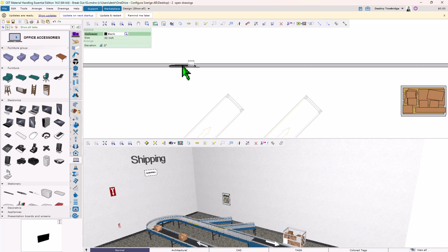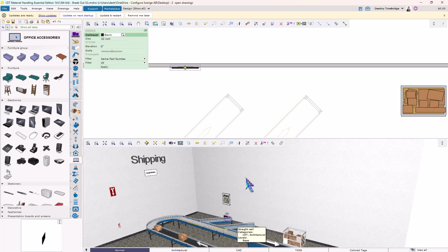I'm going to put this up over that poster that we have. So I'm going to put it here in my 2D view so I can get it placed along a wall. It's not going to want to snap to a wall, so I need to just make sure that it's placed sort of next to a wall. So we're going to have a huge monitor up here that's got some information for whoever's working in this area. So let's set this to a 10-foot elevation, maybe even higher. Let's do like a 15-foot elevation.